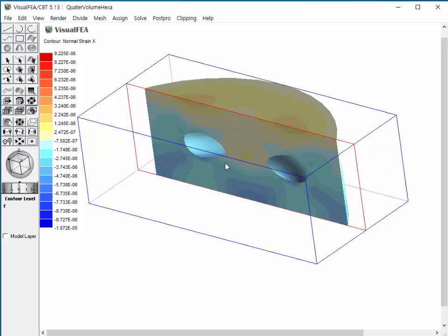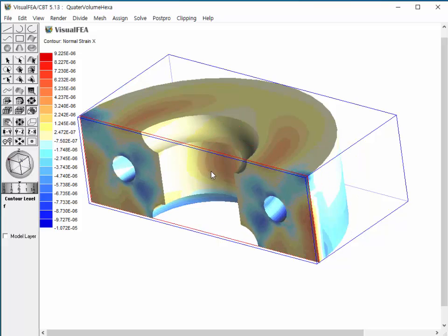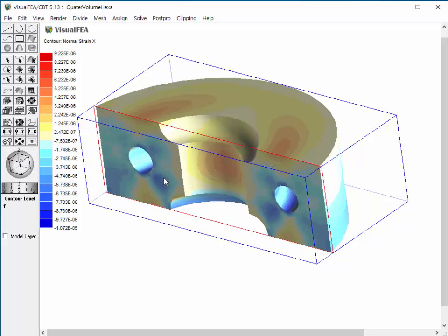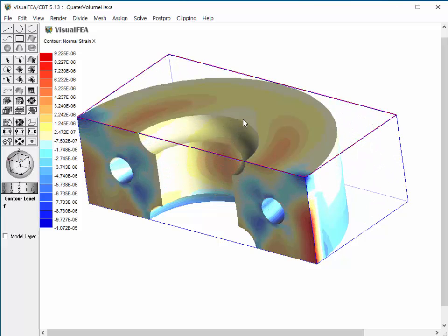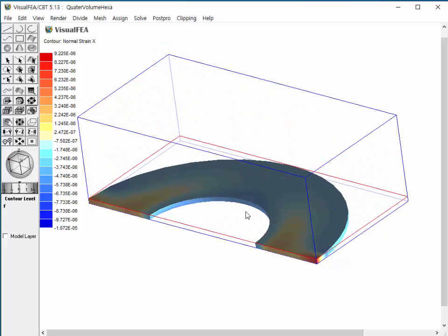The plane can be dragged in the direction of y-axis. Keep placing the cursor on the clipping plane, while dragging, in order to make movement in parallel direction. Double-click an edge parallel to z-axis, then the clipping plane is set to normal to z-axis. In the same way as before, the clipping plane can be dragged in the direction of z-axis.